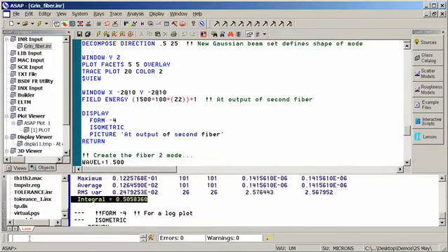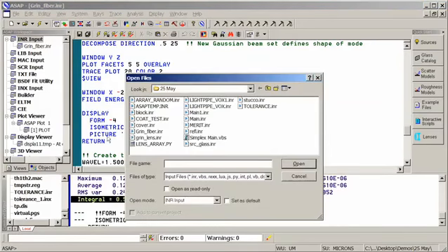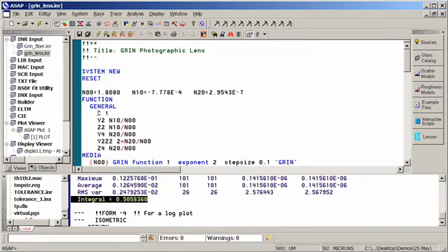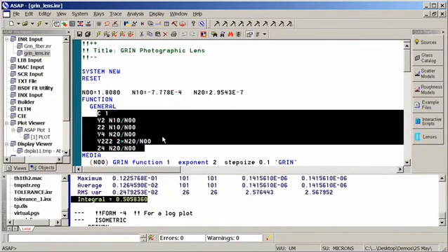In addition to optical fibers, many optical systems have lenses made of gradient index materials, and these are a more large-scale version of gradient index. Obviously, the GRIN fibers tend to be much smaller in diameter. But we also have gradient index lenses, and to define a gradient index material, you'll simply need to define the manufacturer's parameters that describe the properties of that optical material and define a media that then uses those properties.